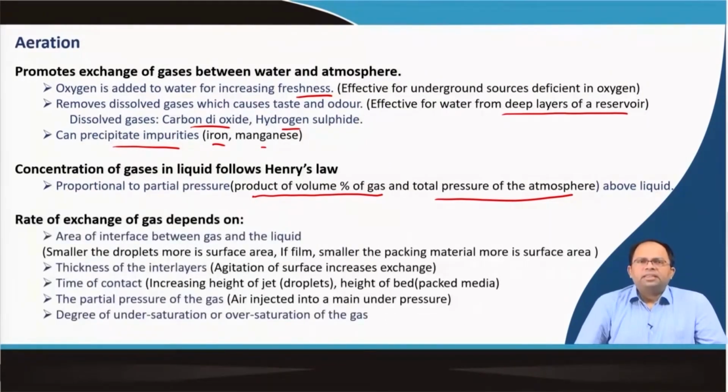The rate of exchange of gas depends on many factors, and these properties are utilized to design different kinds of aerators for the water treatment process. What are these properties? First, the area of interface between gas and liquid. The more the area, the more the exchange. Smaller the droplets, more is the surface area. So, if we make the water droplets smaller, we increase the area of interface between gas and liquid.